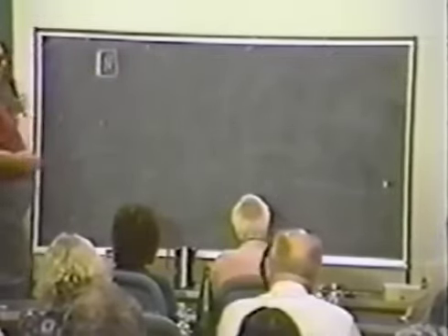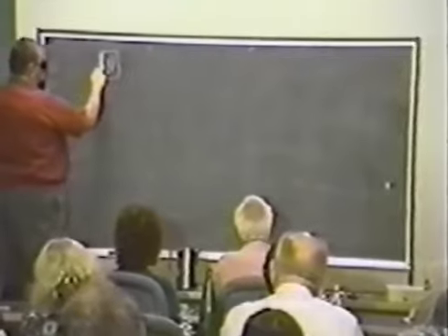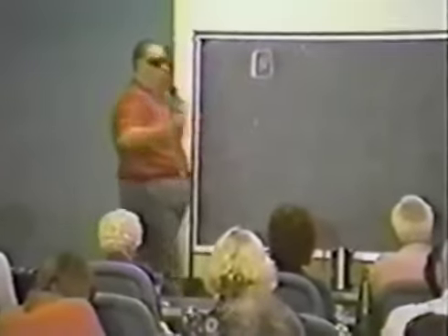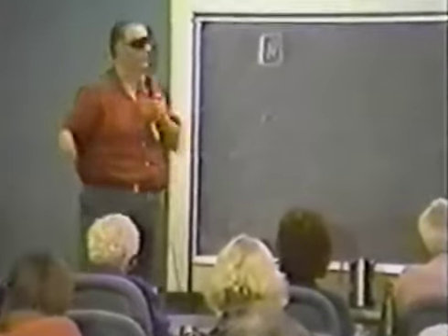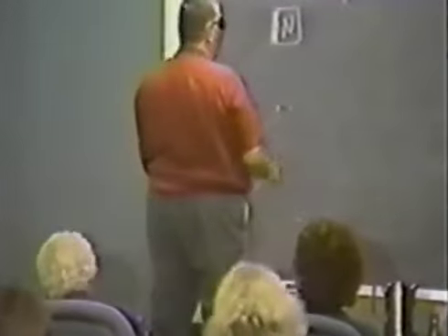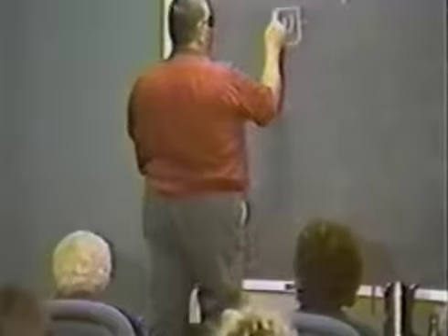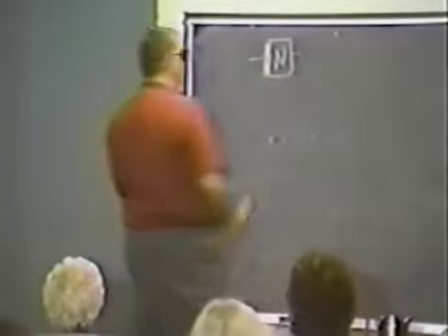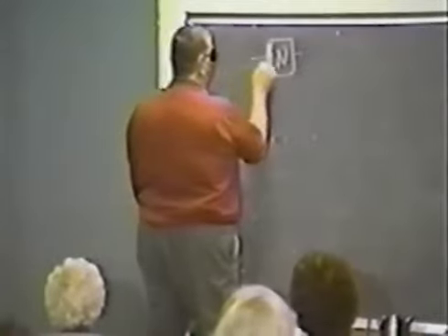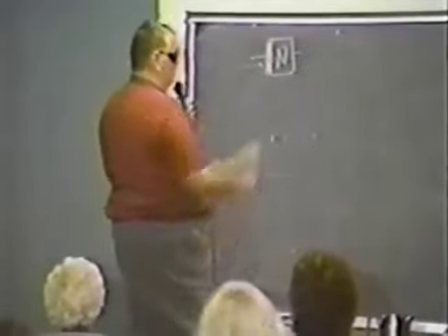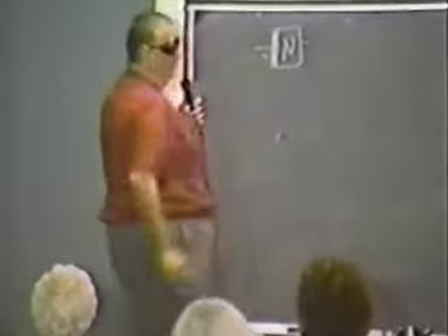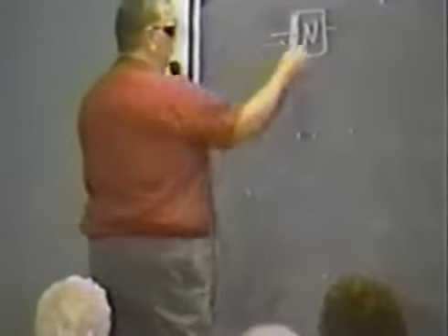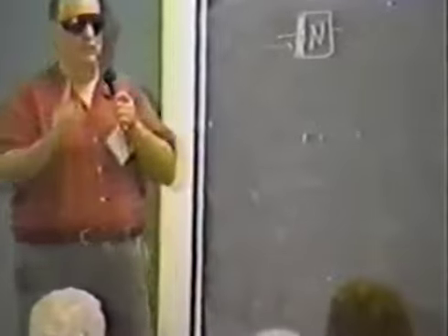Now, because of the electron pressure coming up here, hitting the barrier coming back, it builds a depletion region without putting any polarization across it. Notice this thing with nothing has a depletion region. Now, if you put a current through this, what's it going to do? It's going to build up electrons on one side or the other side of the barrier. When you reach a particular point, they're going to punch through the barrier. But it's not a punch through, they tunnel.